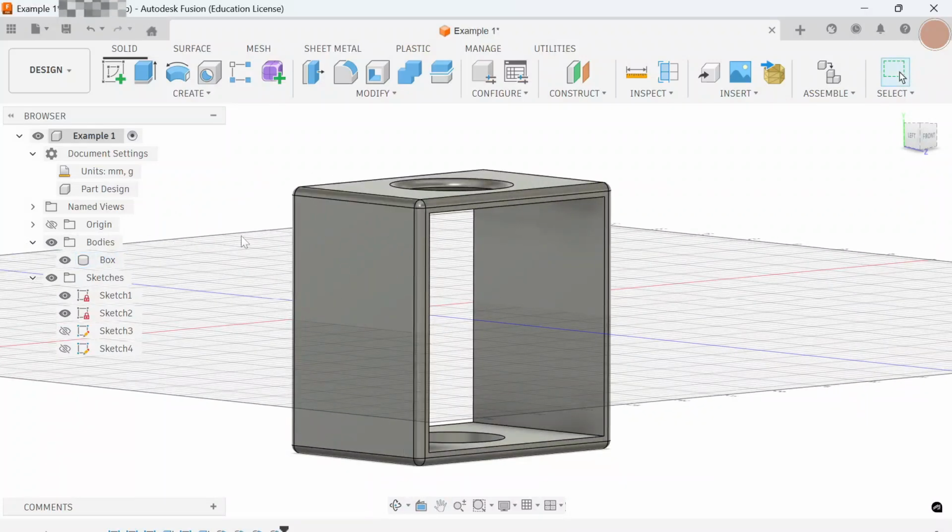That's how you turn a 2D sketch using Extrude into something 3D. You can do it thin here like I showed you. You could have extruded it as a solid block. You can use Extrude to cut things. You can also use fillet to curve edges in more than one way, with the rolling edge or the setback edge. And you can choose how much you want the edges to be curved or not at all, depending on what you're trying to build.